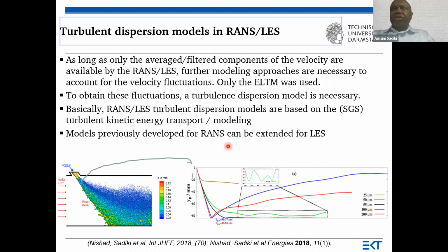So that is everything I have told, and we will try all the examples I have told you. We use this dispersion model, the eddy lifetime model, and the model we use for RANS can also be extended for LES. And here I show you the effect of turbulence dispersion. For example, we follow one particle here, and we see that if we inject one particle, it will impinge the wall and change the trajectory.